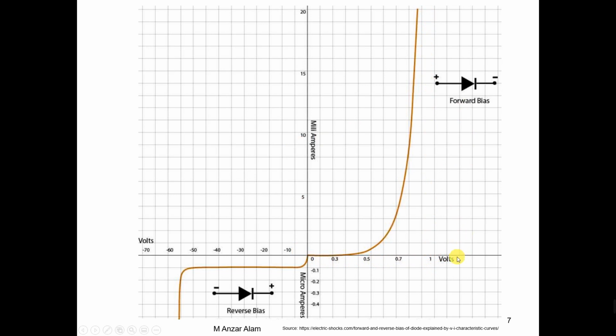If we extend far enough to meet the characteristic curve, probably at a very large distance we can meet it, and if we go upward the scale will change, not in milliampere but in ampere, at a very far away point. The operating point is far away, where the vertical current is 300 amperes. So the operating point is at voltage 1.2 volt and current 300 amperes.